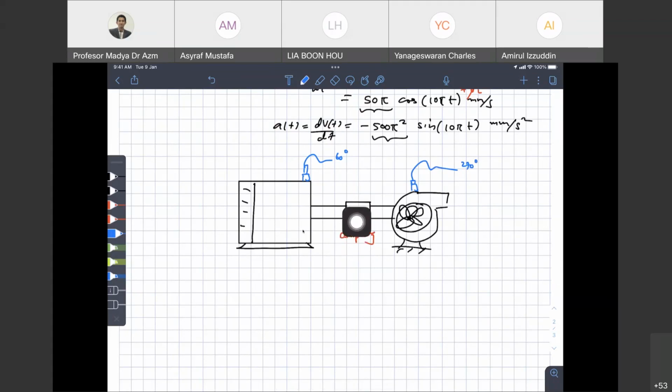It means that this one goes up, this one goes down. So there will not be a good coupling. Good coupling to determine means that there is a flexibility in the coupling. So you have to do something with the coupling so that everything is in phase. That one is in practice as well, to troubleshoot the vibrations, the problem of the vibrations.